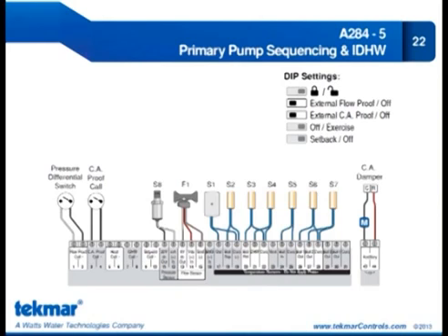And then in that case, you could use the combustion air damper terminals for a combustion air damper too, right? Yeah, well, even regardless, right? The nice thing about this control is there's a separate input for flow. So you could, theoretically, if you look at terminals 1, 2, 3, and 4, we have a dedicated terminal for flow proof.